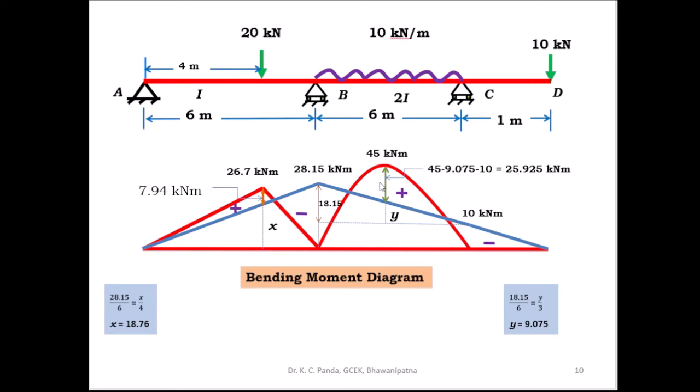The maximum moment you can find where the shear force is 0. So after plotting the shear force diagram, you have to find the zero shear force position, and at that position you get the maximum bending moment.